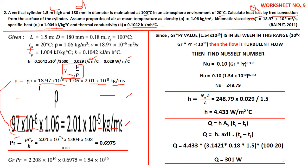Substitute this mu value. Cp is given in the problem, but be careful, it is 10 power 3, because in the question Cp is 1.004 kilojoules, so multiply by 10 power 3. K we know, 0.029 thermal conductivity. Okay, then you will get Prandtl number as 0.6975.